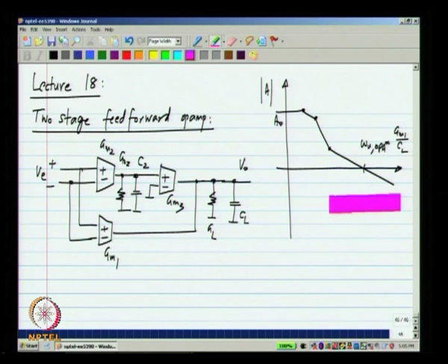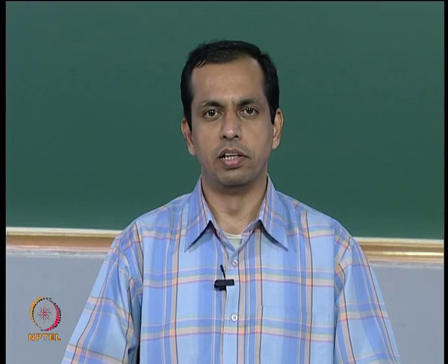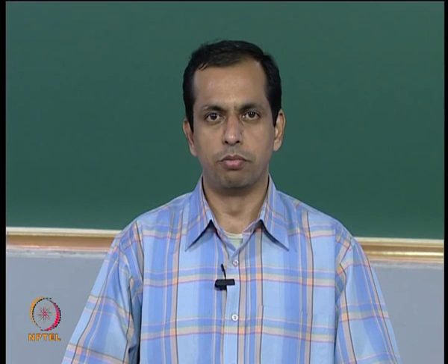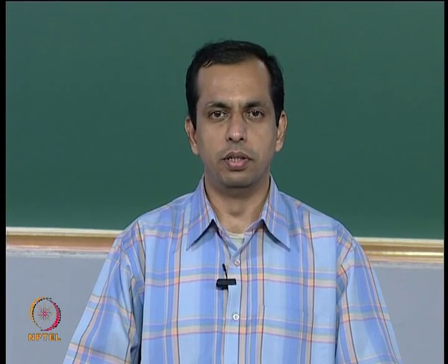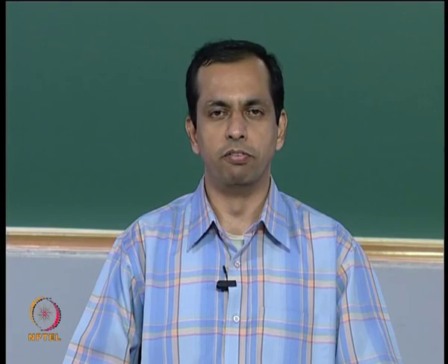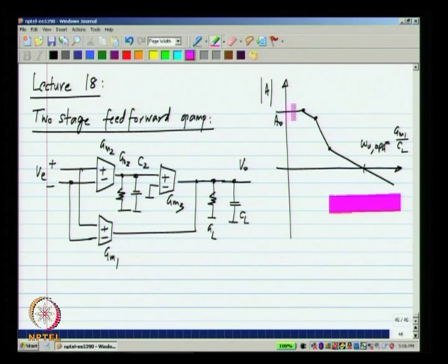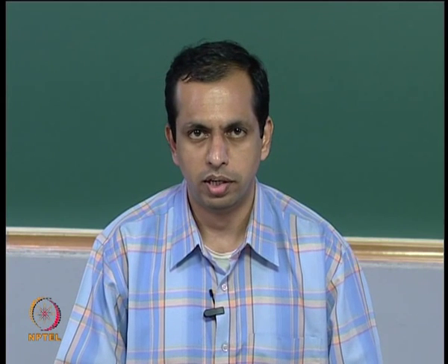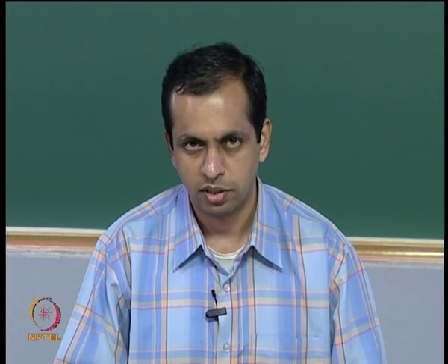We know that the stability criterion, which is the Nyquist criterion, talks about encirclement of -1, 0, which relates to how the loop gain curve behaves around the unit circle, where it enters the unit circle from. So, we have to model this part accurately, but this part around DC is not so necessary. So, we will act as though the DC gain is infinite, which is clearly unrealistic. As I said, it is because of finite DC gain that we go to a 2-stage structure and 3-stage structure and so on, but here we are only looking at stability.